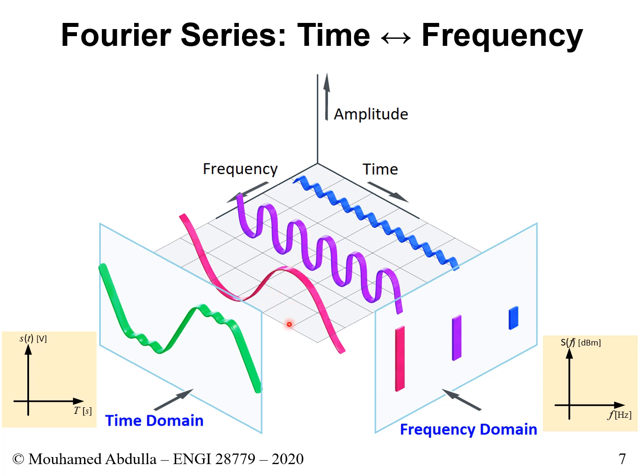Now, in the figure here, they didn't show you the fourth harmonic, the fifth harmonic. Perhaps it exists, perhaps it doesn't, but they dropped it. They could not show it in the picture. But in the end, if you add all of them, and that's why it's called an infinite series, because you have infinitely many of them, you add all of them, this should get you your signal back. So we take the signal, we break it apart, and you get all these different components. Now that we have these components, we'll be able to represent it, to project it on something on its frequency.